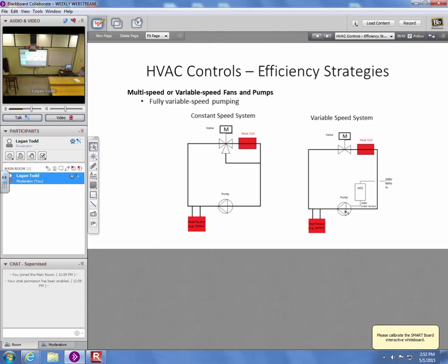And now the affinity law comes into play. Like was said earlier, if you don't have a VFD and you're trying to do this affinity law thing, the pump just rides its curve, the motor gets partly loaded, and your efficiency is lost because of the dive in motor efficiency. But if you can vary the pump speed, you maintain your motor efficiency and you get a real payback.